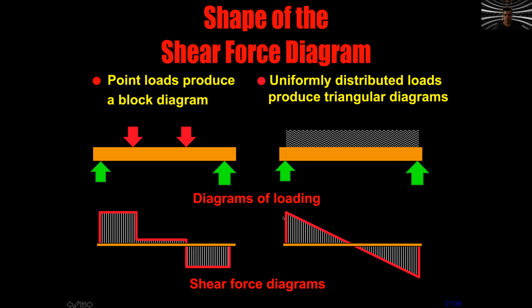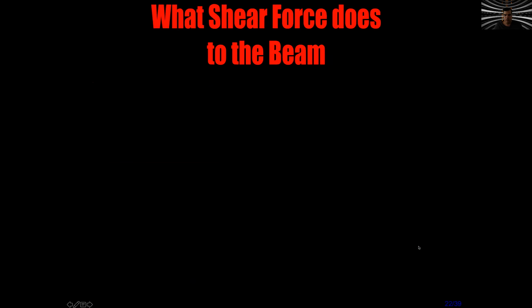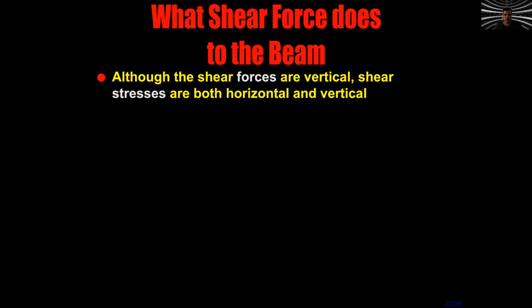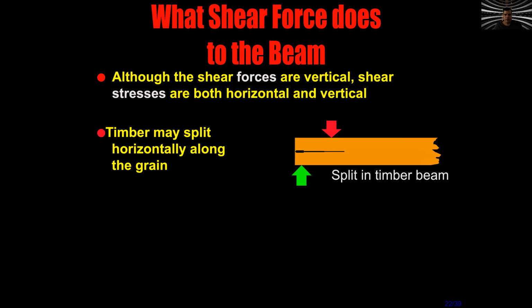Because the force will go up, and little by little, each one of these elements has a particular value that is pushing down, and little by little will be going down. If the total value here is, for example, 100 pounds for the full distributed load, we go up 50, that is half because it's symmetrical. We go down little by little, 100, we arrive at minus 50, and we go up 50. Well, I know that you already know this, but it's just a review.